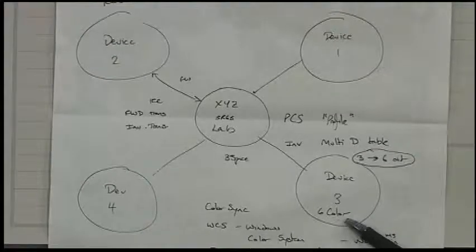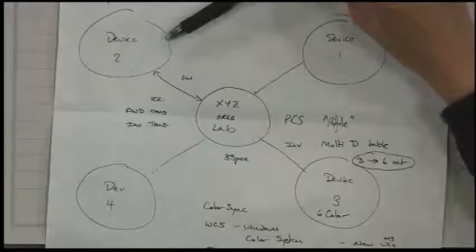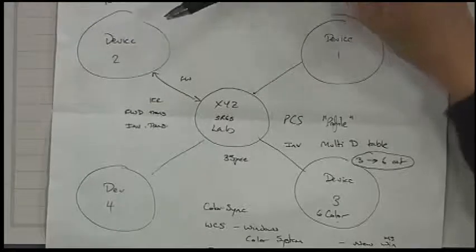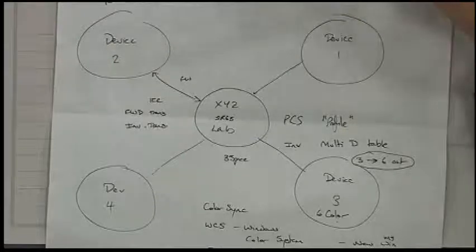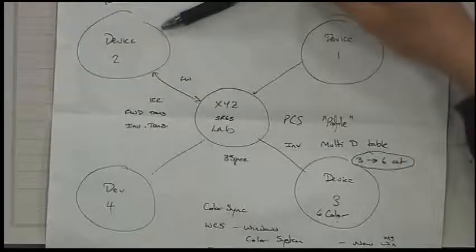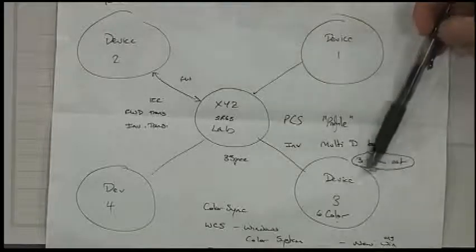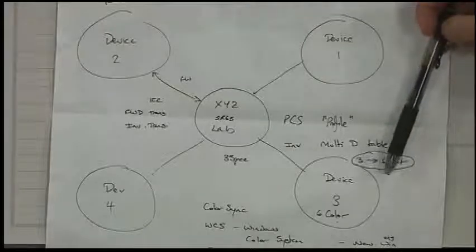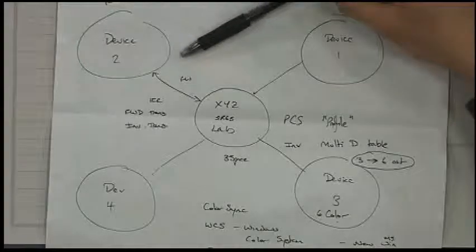Because the sensor of the camera defines some kind of native color space, the RGB values the device captures have to be relative to the native color space of the camera. So we need to make sense out of these 3 values so that we can print the colors in a way that looks similar to what we actually captured.